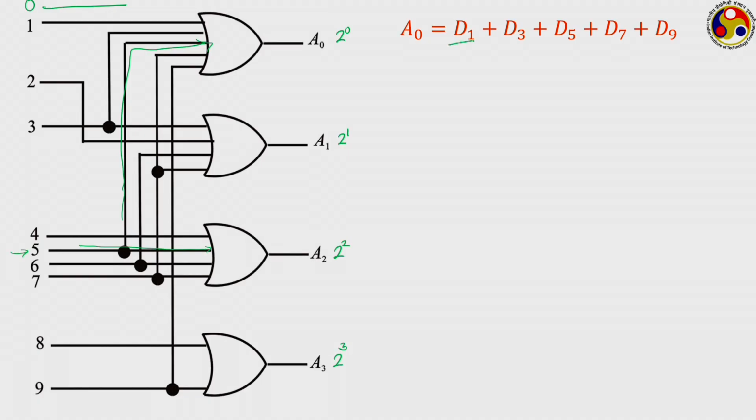Whenever you are pressing 1, it is switching on that line and an electrical signal is going in the form of this D1, and accordingly it is being activated as this A0 switch, and it is giving a 1 in the least significant bit, in the A0 position. But follow this 1, it is connected only to this A0 because you need the other 3 bits to be 0. So, you are having 0001 in the 4-bit register.